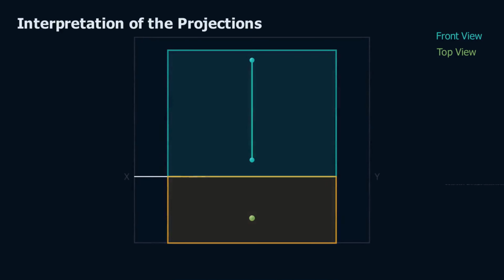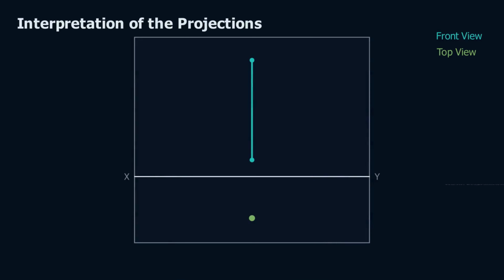The two planes merge into one flat surface, the drawing sheet, with the reference line XY across it. On paper, the views become crisp pen marks, a line, and a single point. Label the worksheet. The front view is the vertical line, a dash b dash. The top view is the single point below XY. We write b first and in brackets because looking from above, B is nearer to the observer and A is hidden directly beneath it. And the point view sits precisely on the vertical projector through the front view. Views always align.